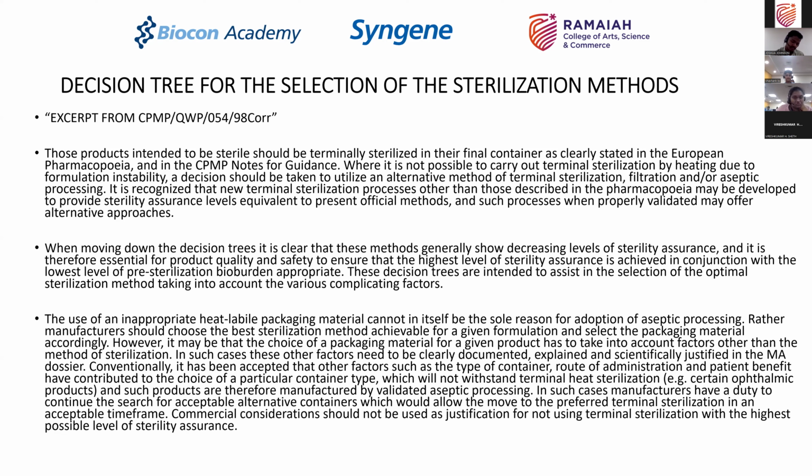There are other processes where you cannot filter the product, like if you were dealing with suspensions or dealing with emulsions, they may not be filterable. So in that situation, even your compounding vessels have to be now free of microbial contamination. So right from the first step of manufacturing till the last stage, you are not able to terminally sterilize the product, and therefore you have to make sure that at every step your sterility assurance is there.